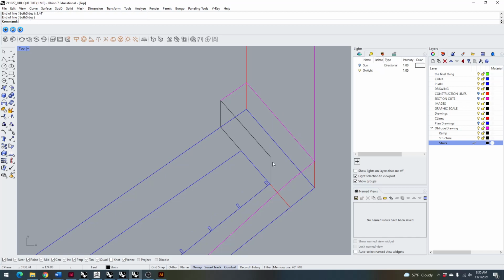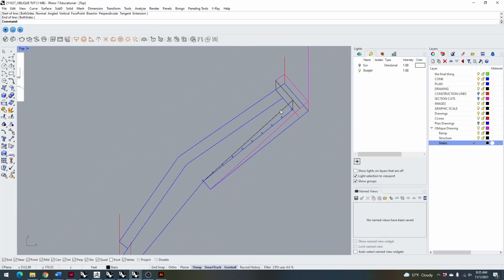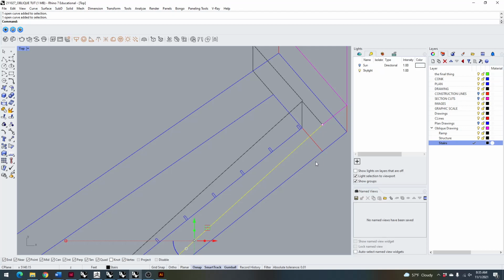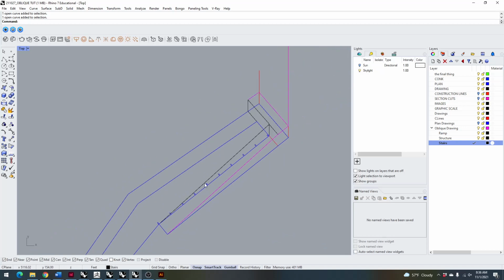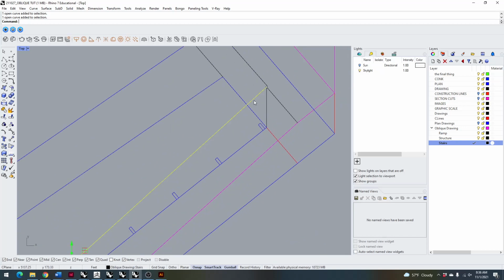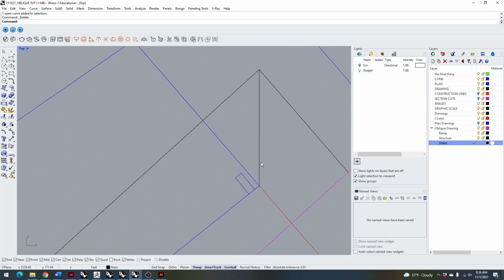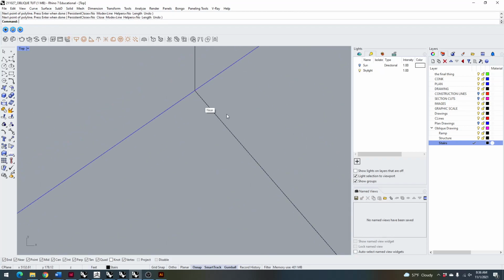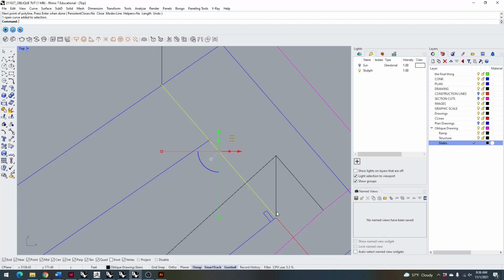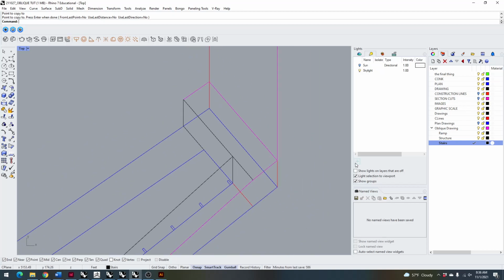Draw a line up there at 3.44 feet. And then a line back there. There's some difference between the widths of the ramp between the bottom and the top that was causing a difference in the angle that this line occurs in the plan oblique. So I think I was being a little bit lazy when I attempted to just directly correlate them, and it caused problems. So if you're overly lazy in your attempts to find symmetry, you may end up with problems down the road.